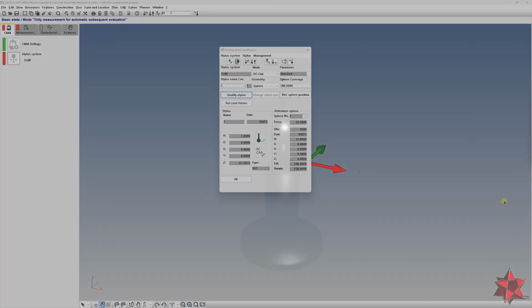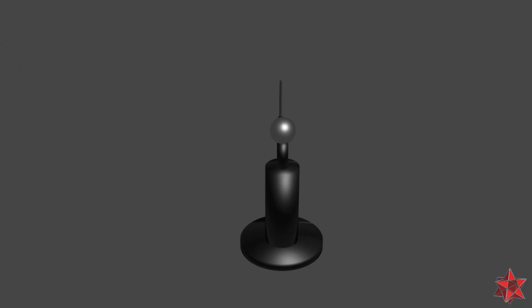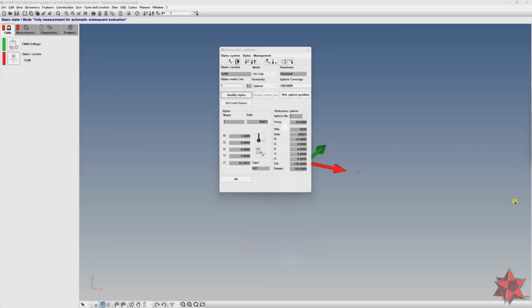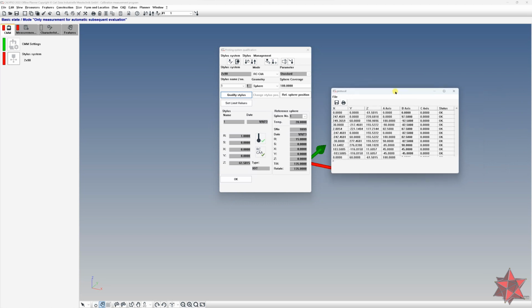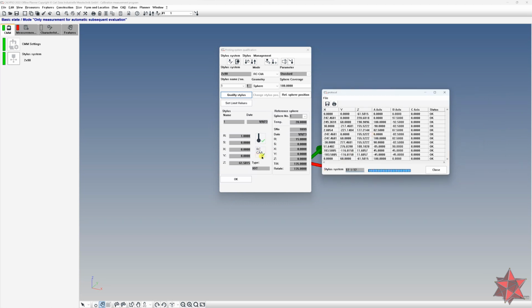Next step is to touch a point on the center of the reference sphere with this stylus as well. After this point is touched, the calibration process will start and the stylus will calibrate the 12 angles from the RCCA. As a disclaimer, if you have angles that do not correspond to the initial position of the reference sphere, or if you use two reference spheres, then you have to group these angles separately and measure them after you finish with the initial setup.